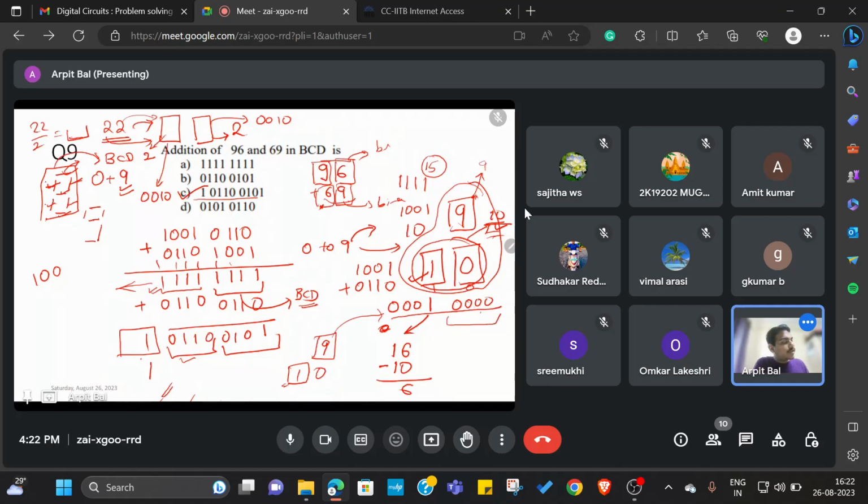And if I convert from BCD to binary, then it is going to be 16 in binary, right? So this is the decimal equivalent of that 16, and the original number would have been actually 10, because if you increment from 9 it is going to be 10. So the difference is 6. It means I need to make a correction of 6, right? So that's why I added plus 6 to this digit. Okay, then this is the answer that we arrive at.